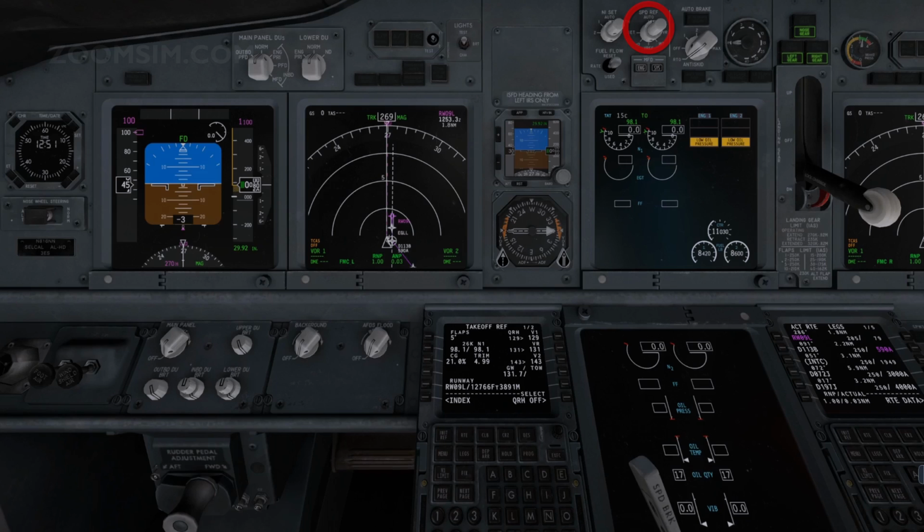Speed reference, auto. The speed reference selector sets the reference airspeed bugs on the Mach airspeed indicator. It has 7 positions: automatic, V1, VR, WT, VREF, bug 5, and set. In the automatic position, the reference airspeeds and gross weight are provided automatically through the FMC. The V1 position is used to manually set decision speed on the ground. In flight, invalid entry is displayed.